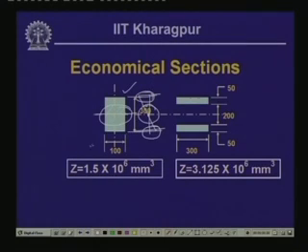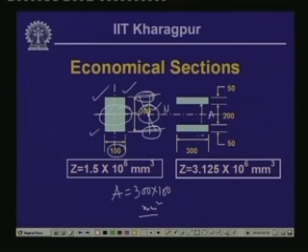Now in this rectangular section, we have a dimension of 100 millimeter width and 300 millimeter depth. So the cross sectional area is 300 times 100 millimeter square. Now let us say we utilize the same area, but we place the masses in such a way that they are at a distance apart from the neutral axis. This is the neutral axis. The width of this segment is 300 millimeter and the depth is 50 millimeter, and we have two such segments which are away from the neutral axis.